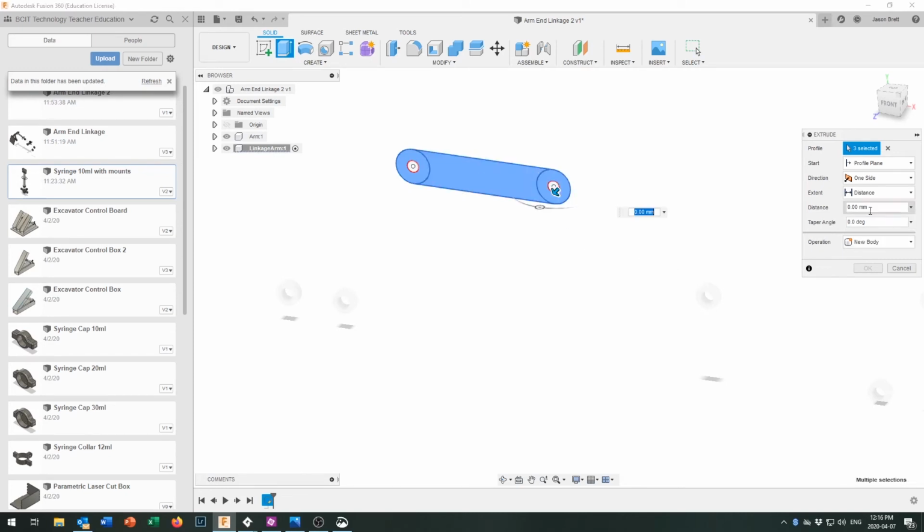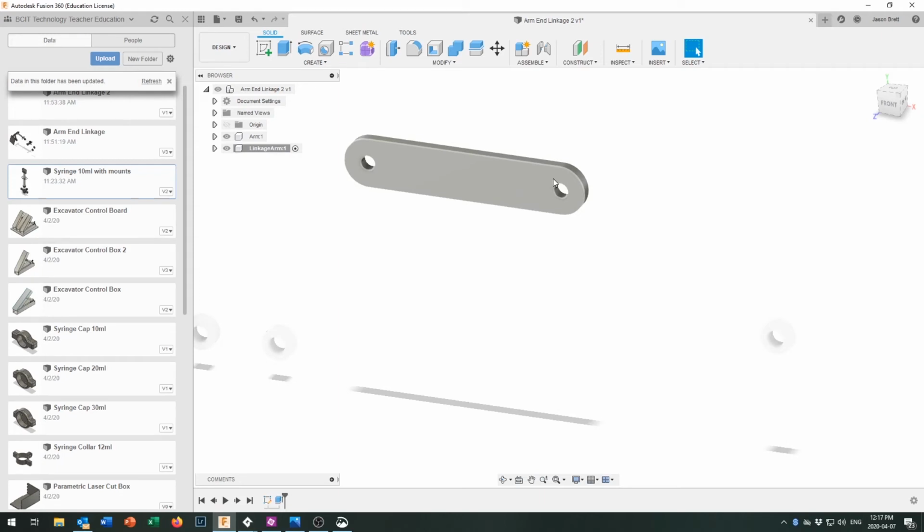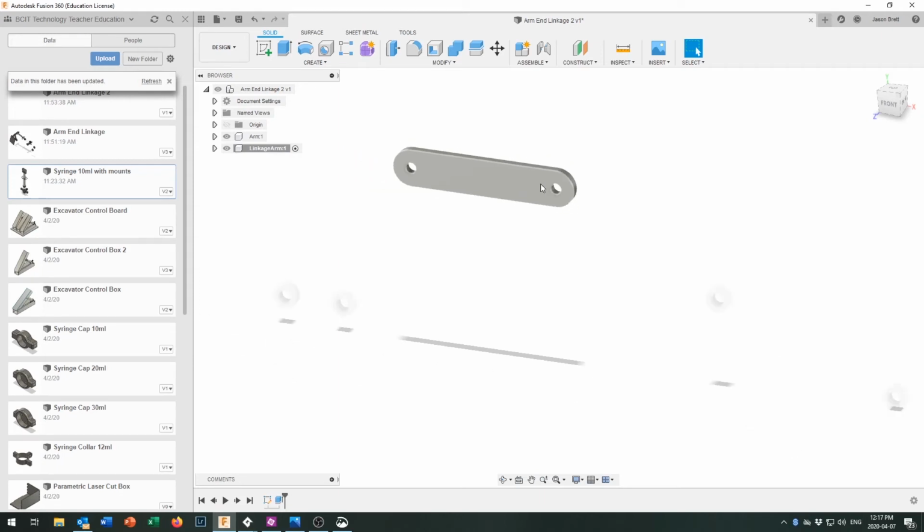We want those 3 surfaces right there, and we'll extrude at 3 millimeters. Now I should probably be doing that as a parameter too. We can parameterize a lot of things when we do this, but I'm just working on the assumption that we'll use laser cut MDF, 1/8 inch MDF, 3 millimeters. Okay, so that part is all created in there and ready to go.